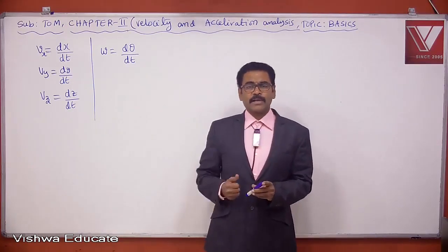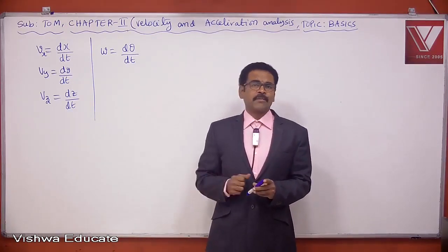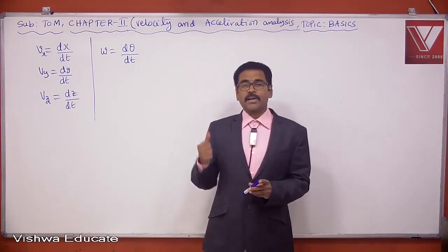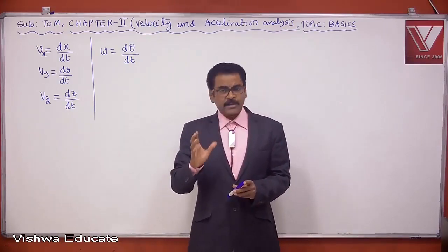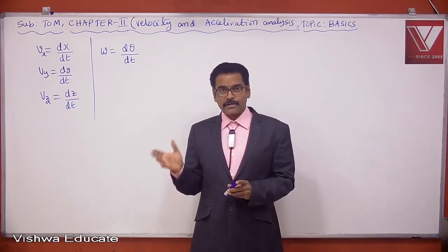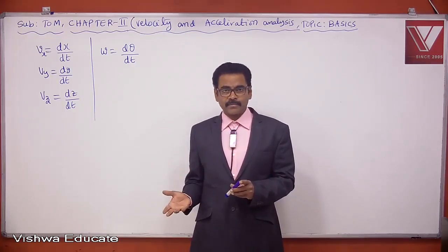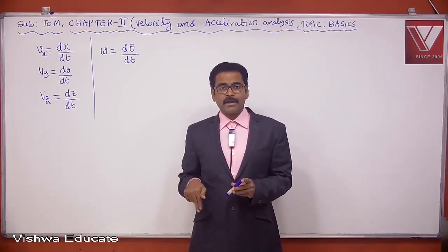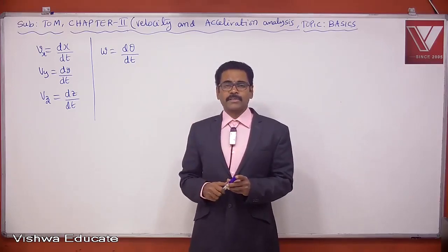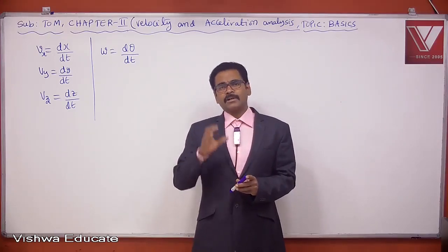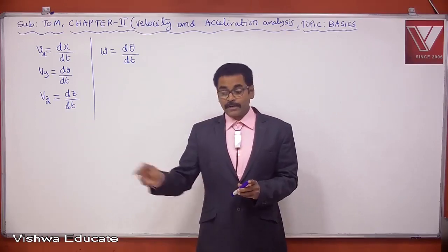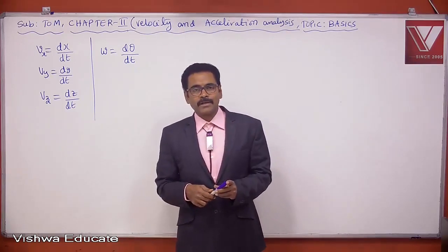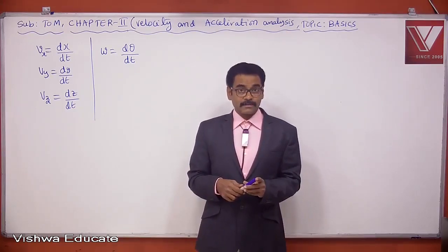What is lowest force? What is highest turning moment? What is lowest turning moment? So fixing of forces and turning moments of various links for new mechanism, or calculation of force carried by each link and turning moment carried by each link of existing mechanism is called force analysis.